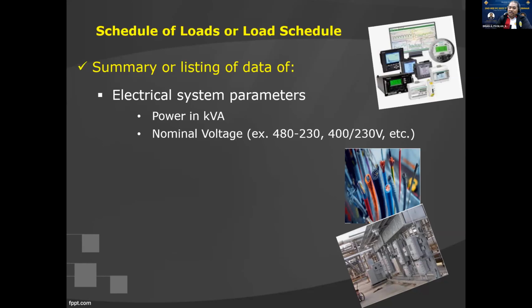So ito yung may step down transformer from 480 to 230 volts na mga small power loads, no? So ngayon, we adopted IEC. Ito yung si 400/230, may neutral loads na ito, line to neutral loads, no? Yung mga single phase loads natin. So advantage of this one, wala tayong need for step down transformers, no? We can utilize, no, the neutral connection to get the phase voltage of 230 volts to supply the single phase loads natin. Okay? So I know familiar kayo dyan.